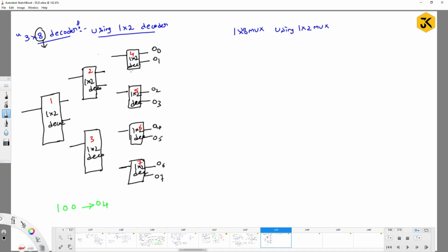So basically guys, try to observe, for every decoder or for any kind of circuit, there will be one more line called the enable line. What is the use of the enable line? It is meant for whether to switch on the circuit or switch it off. I can use the enabler, right? So here I am trying to use the enabler to control the respective circuit. What is required here, I am not passing any input, I am just passing the voltage. That's why I am just simply activating it, right? So I can make the connection like this.